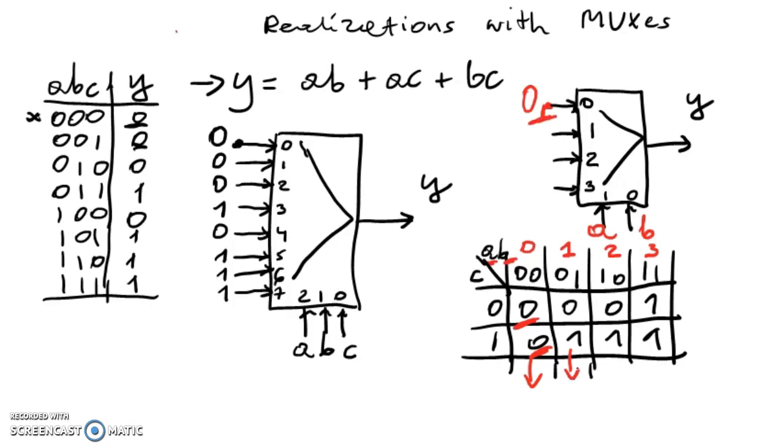The next column tells you that for A0, B1, so if you select input 1, A and B, select input 1, you've got 0 for C0, 1 for C1. So it follows, yes, this should follow C. So that's why we put the variable from the outside world. So not a static signal, but it can change. It is the third input of the voting machine, of the majority of ones detector.